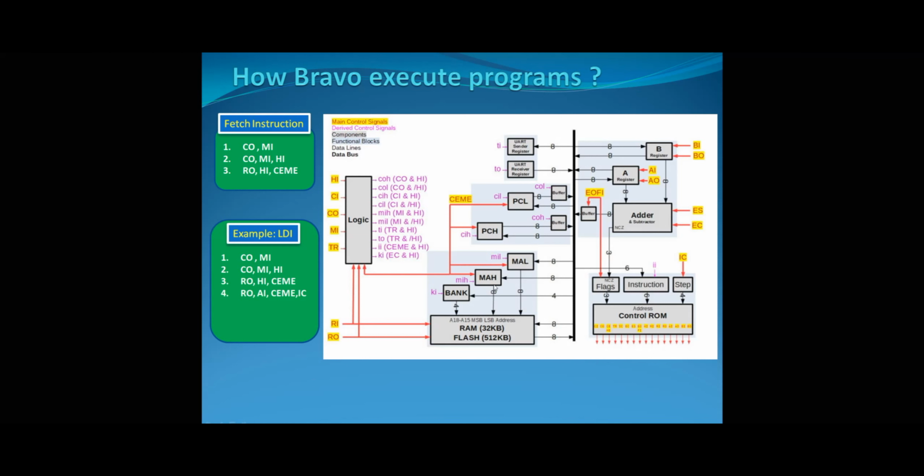And the same thing for the memory address register. On the input side, the memory address register is also 16-bit, but the bus is 8-bit. So again, we needed two clock cycles to read the content into our memory address register. However, the output of the memory address register is directly connected to our RAMs, and that one is 16-bit in general.